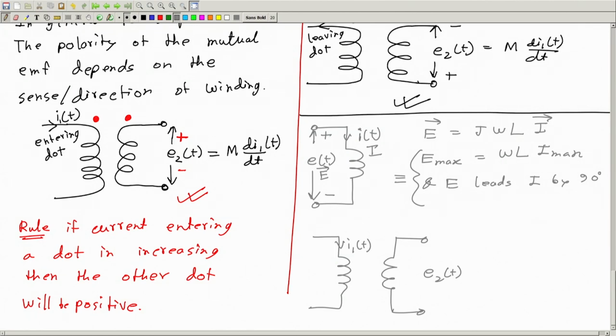Without the sign, this is meaningless. Okay, that's important. So here also, I have put the symbol for the current. Similarly, I put the symbol here, and then I put some dots. I should actually put the dot first and then the symbol. Okay, so I put the dots, and then this current is entering through the dot, so I choose the reference direction in this way.